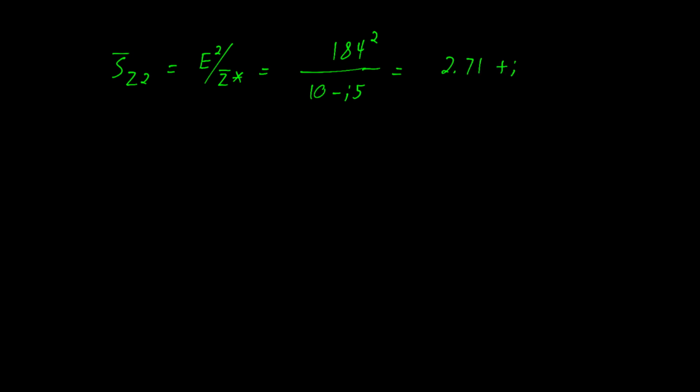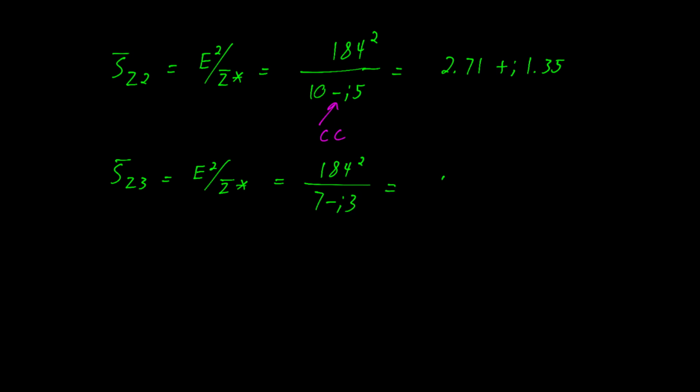To get started, we'll calculate the complex power of impedance 2, because I think that's one of the easier ones to do. We calculate that as a voltage squared divided by the complex conjugate of the impedance. Don't forget, it's negative J5 here because we need the complex conjugate. Solving for that, we see that impedance 2 is 2.7 plus J 1.4 kVA. We solve for impedance 3 in the exact same way, yielding 4.1 plus 1.8 kVA.